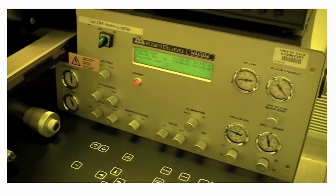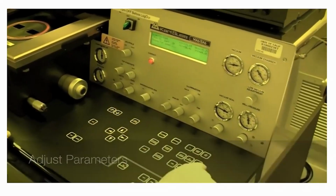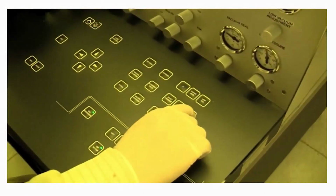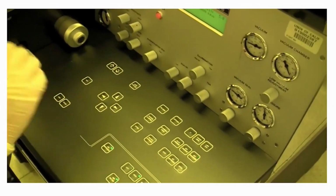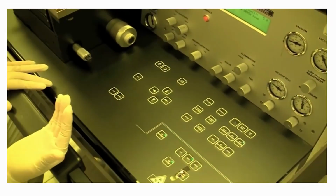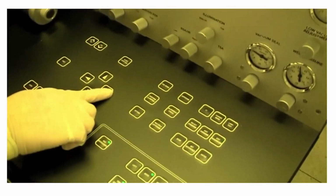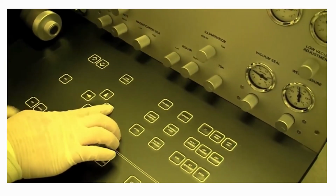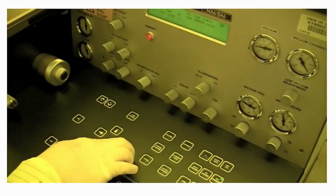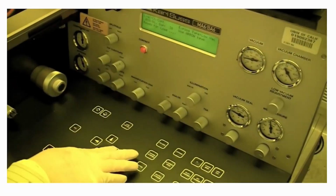So before we run the machine, the one thing we can do is change the parameters. So you hit this button called edit parameter. And now you can adjust the parameters such as time and gap distance and type of exposure. So how do we edit the parameters or change the different parameters? We can use the X left and right. So we move this way. You can change the gap, change the type of contact, and then change the exposure type.